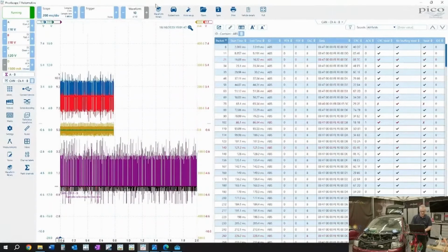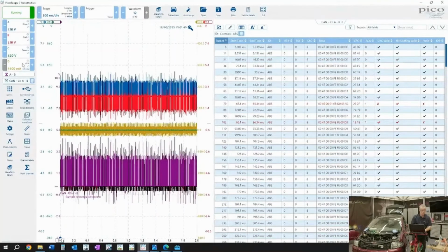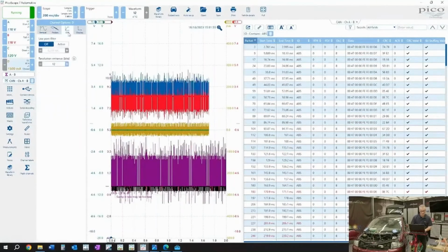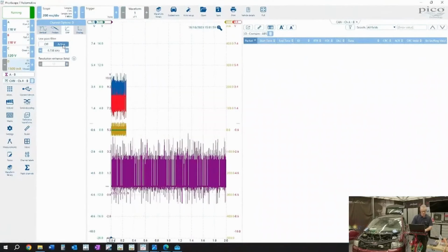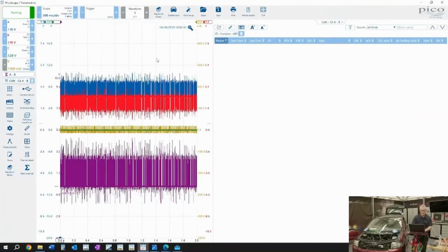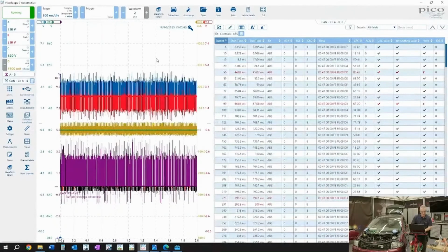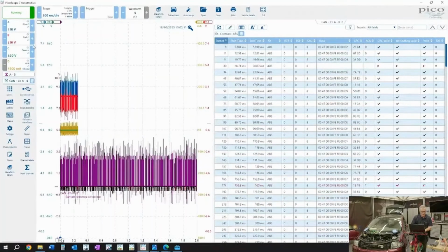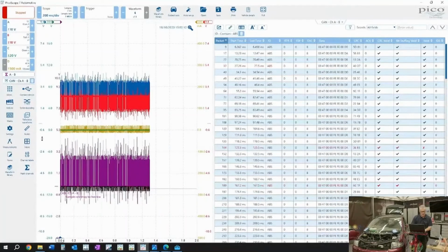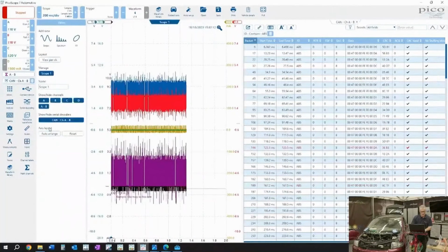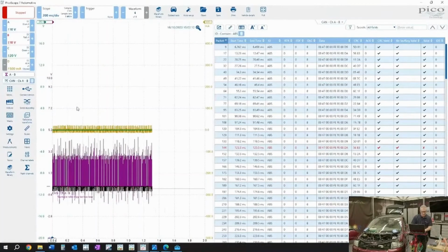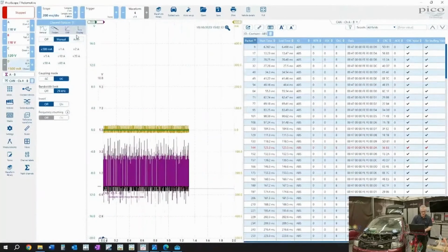We have to make some tweaks here because there is a lot of noise on this signal. So first of all, we are 500 milliamp. We want to add some filtering, so we'll make the filtering active. So you'll see in a second that at the end of the buffer, notice how channel D just minimizes. In fact, let's clear this display up because we don't need to see a lot of what's on channel at the moment. Because we've got the math channel, we'll take away, using the views feature, channels A and B. They're still being captured, but we don't need them. The current clamp, we want to amend the scaling on there, and I think the scaling on this was something like times 10.